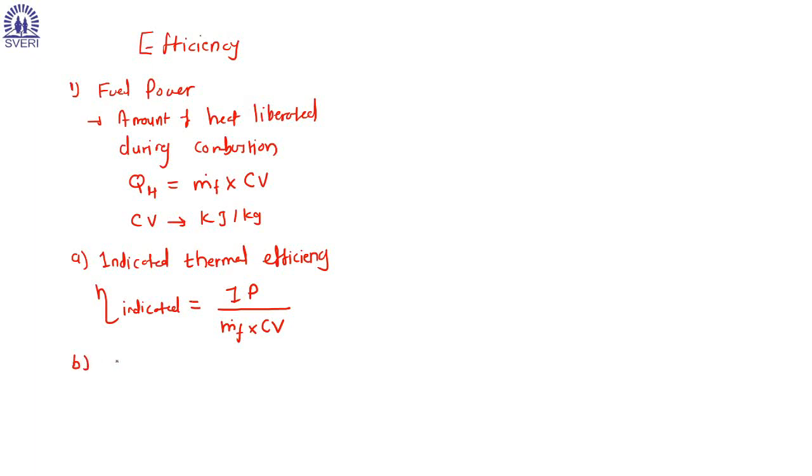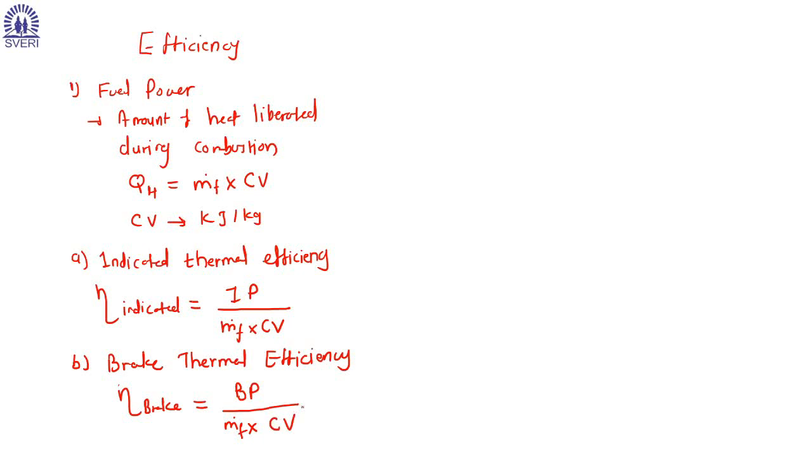Next efficiency is brake thermal efficiency. This brake thermal efficiency is the ratio of brake power to the fuel power. What is the ratio of brake power to the fuel power? That is nothing but the product of mass flow rate of fuel into its calorific value.